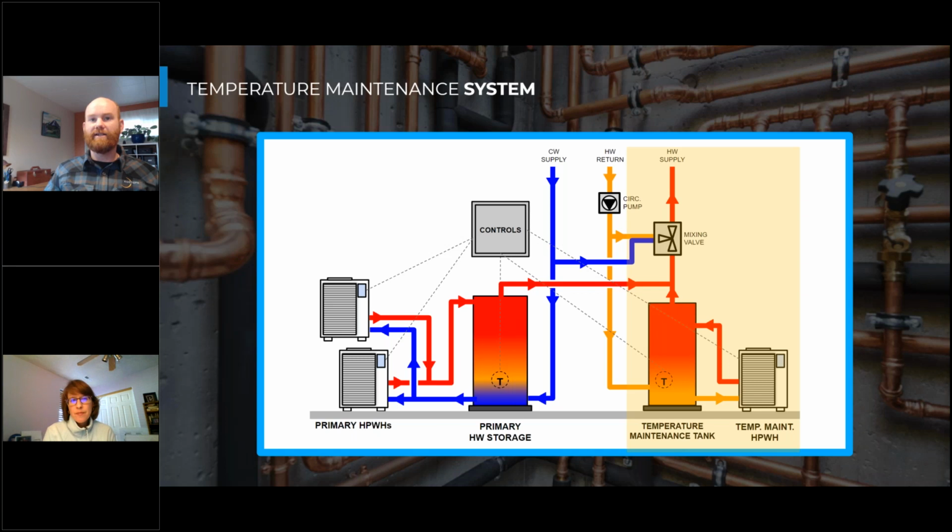And typically we do that just because of physical constraints. But it does mean that there's pipes connecting multiple tanks and there's more heat loss in that pipe than the storage tank. So there's a little bit of a deficiency hit there. But in general, if you can just do one storage tank, that's probably the best. If you need a larger storage volume, then you want to be looking at multiple tanks in series or parallel.